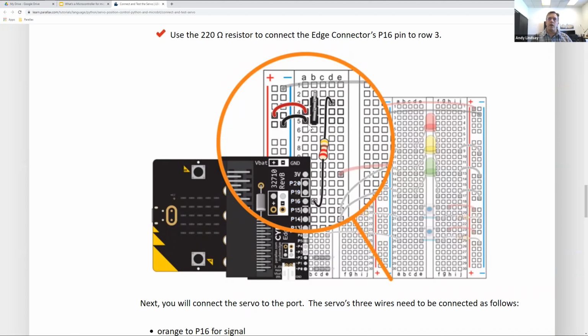Next up, on row 5, that's the bottommost pin of the 3-pin header. And we want a wire that's going from row 5 to the blue column. So we want it to be closer to the blue column, the socket in the bus's blue column of sockets.